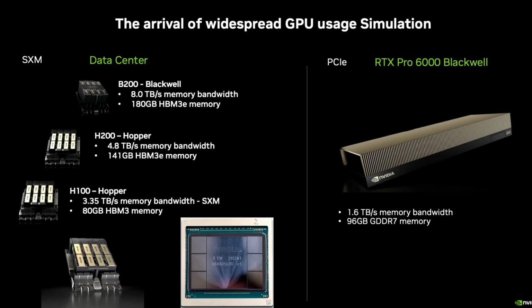If you see that little picture of the GPU here, the key thing with these GPUs is the memory is mounted right next to the GPU. So this is the HBM memory, and this is the GPU. This is what gives us really, really high bandwidth, but it's a more expensive process, this CoWoS process, to mount the memory onto the GPU. But that's a key part of why we can get this super high performance. And you don't get it on desktop GPUs.